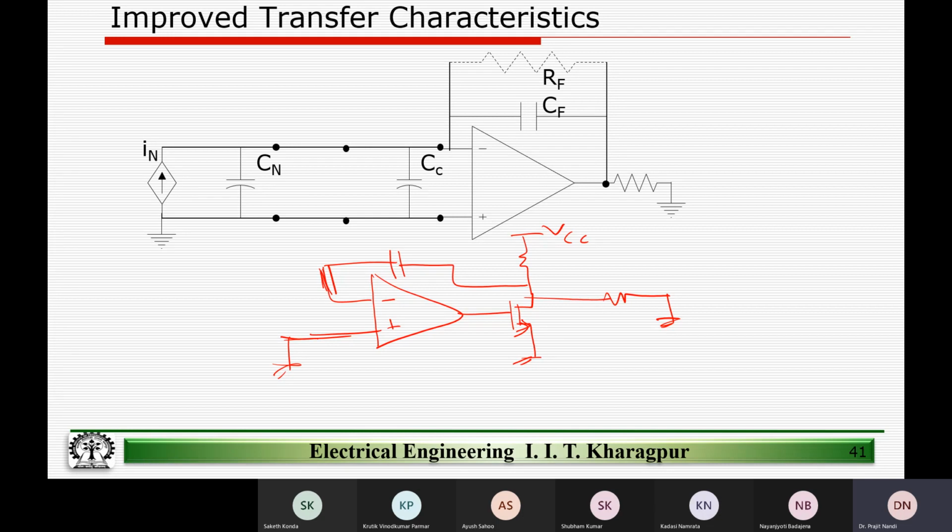So there can be much more complex circuits, and the way I typically quickly understand, and this is again a very simple circuit that I give, whether it's a positive or a negative feedback, is this. This is my output, right? Typically what I do is I say, okay, let me assume the output is going up, and I will try to see what the amplifier is trying to do because of that. So my first assumption is, let's say the output is going up, meaning I'm increasing the output.